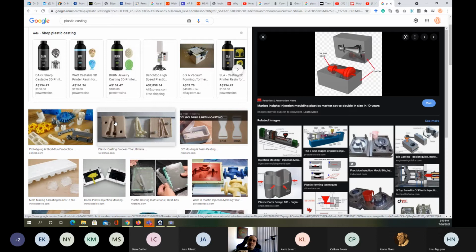You mention that we pour it in the mold prepared earlier, leave it to solidify and cure for 24 hours. Then take the part out of the mold and inspect the dimensions. Those are the steps.